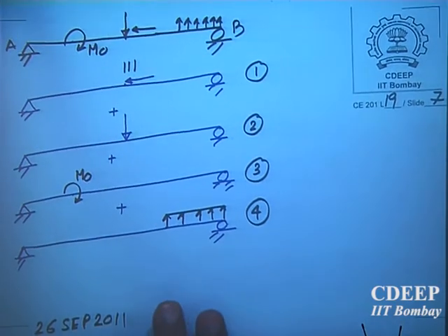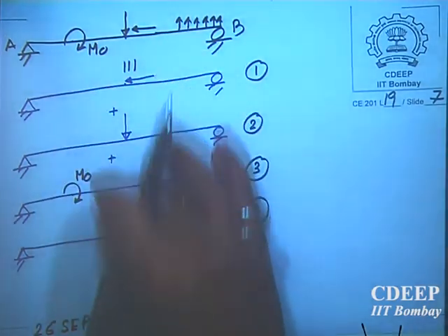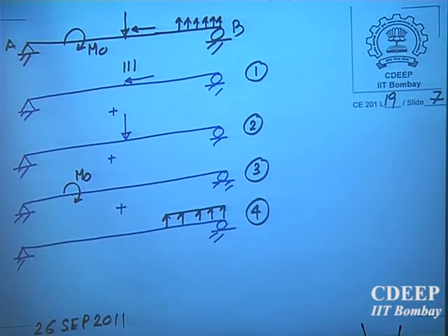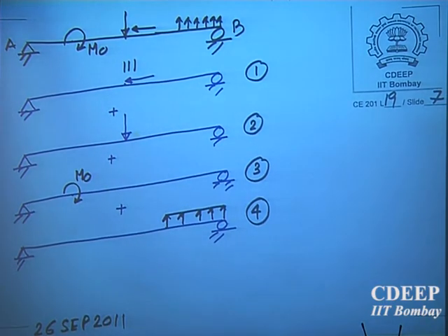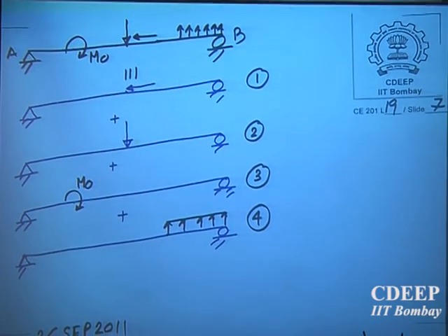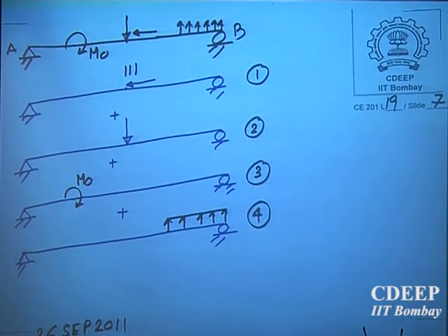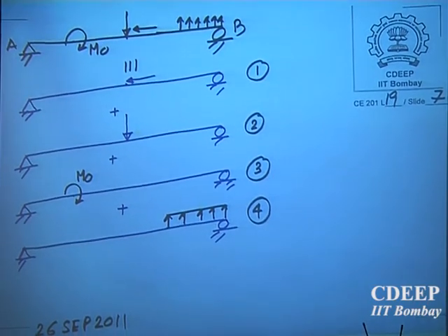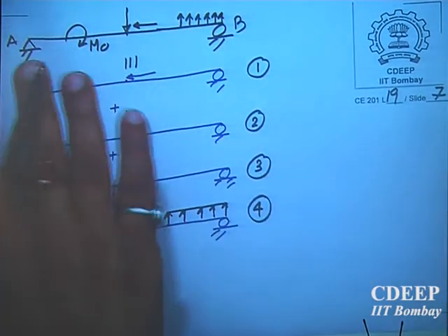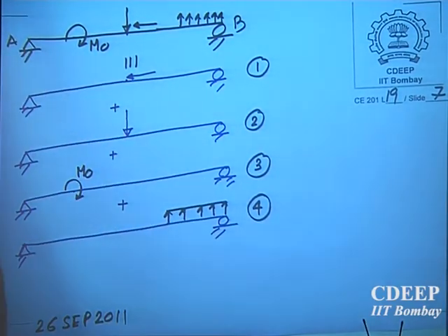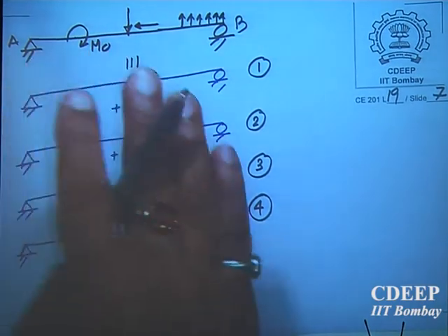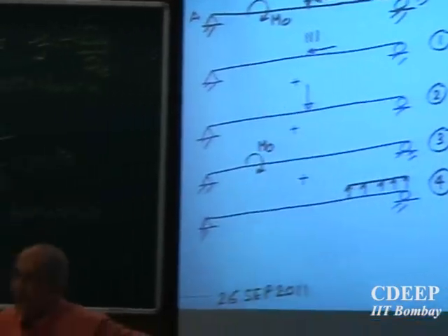See, the total load applied on the system is equivalent to this. So draw the axial force, bending moment and shear force diagrams for each individually. Are you following? Each of 1, 2, 3, 4 separately, and then superpose. Superpose means add one over the other. You get it? So please solve this problem like this also.